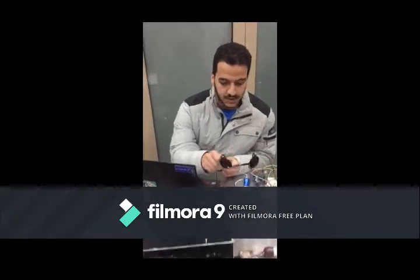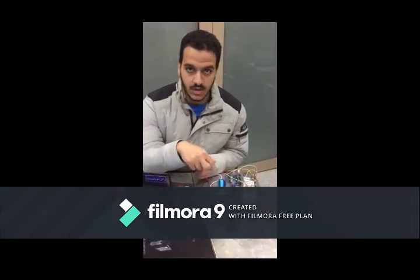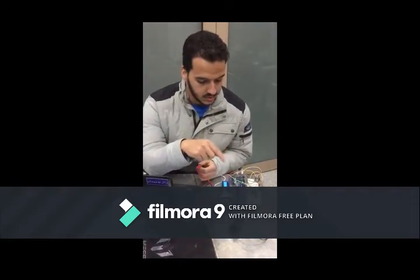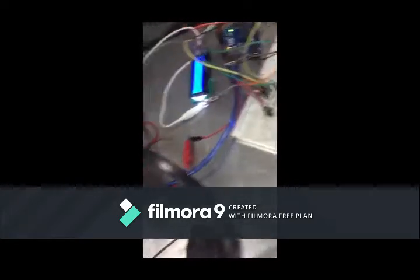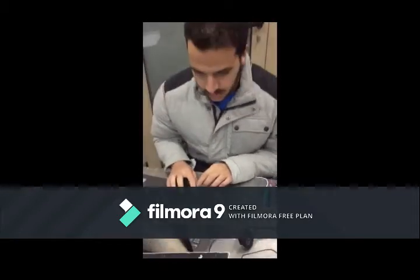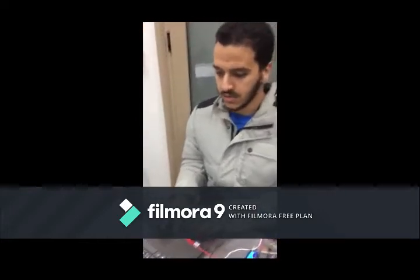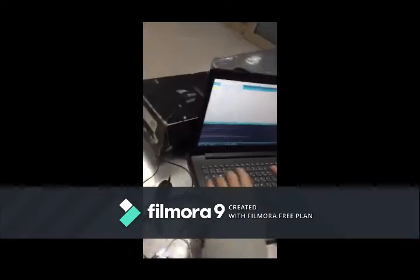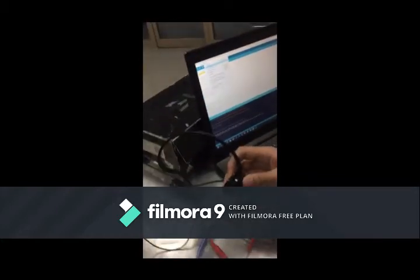The ground of the speaker is connected to the common ground, and the positive is connected to pin 10, which is the output of the Arduino board. And we have these resistors here to protect the speaker from high voltage. And here we will use the serial monitor for the user to write the input, and it will be converted to voice on this speaker.